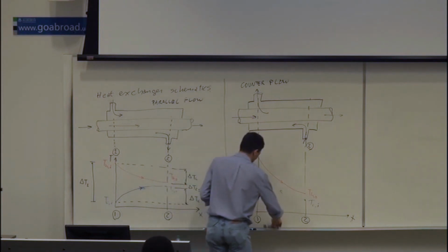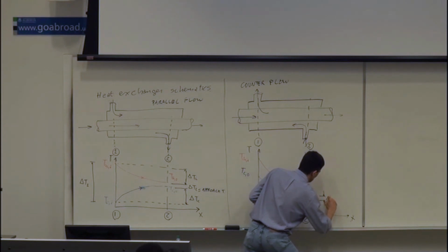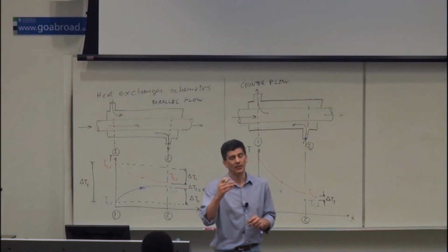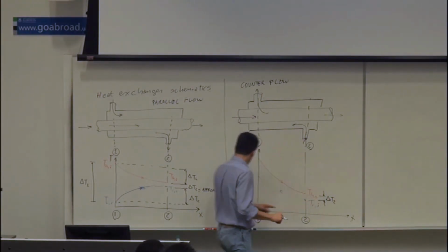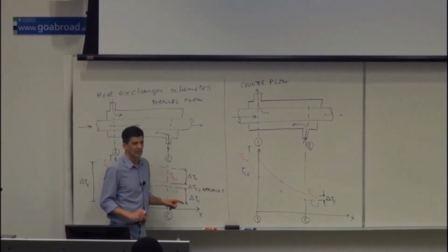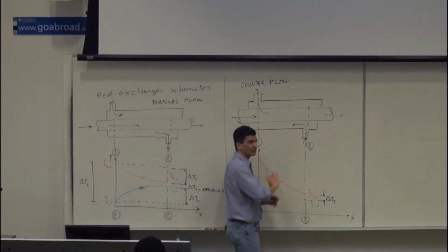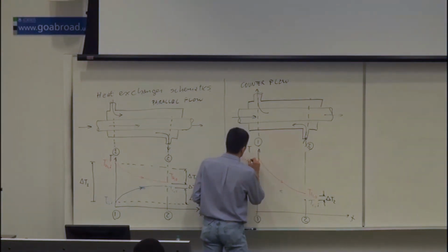And so now we have delta T2. But I draw your attention to this. Delta T2 is a delta T on the side 2, but look, this is hot outlet minus cold inlet. Well, here was hot outlet minus cold outlet. You see? So here you just gotta know what you're doing. Delta T2 is delta T2. It's unrelated whether it was inlet or outlet or whatever it was. And here we have delta T1.